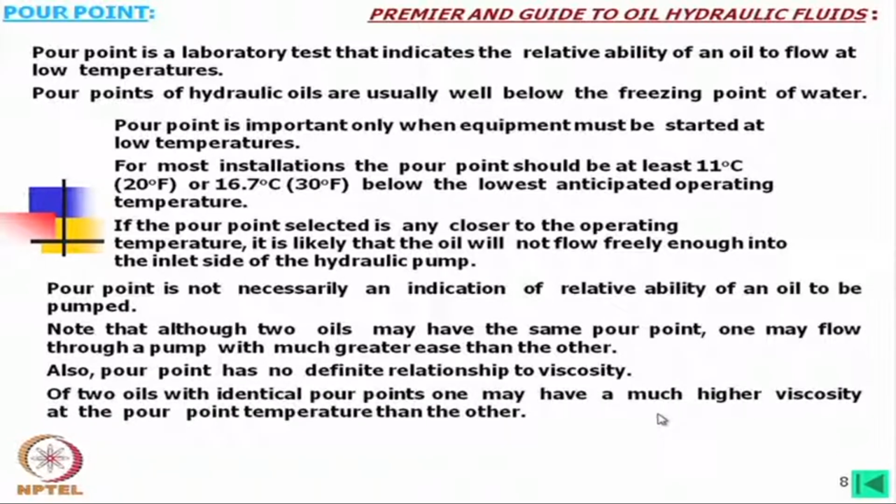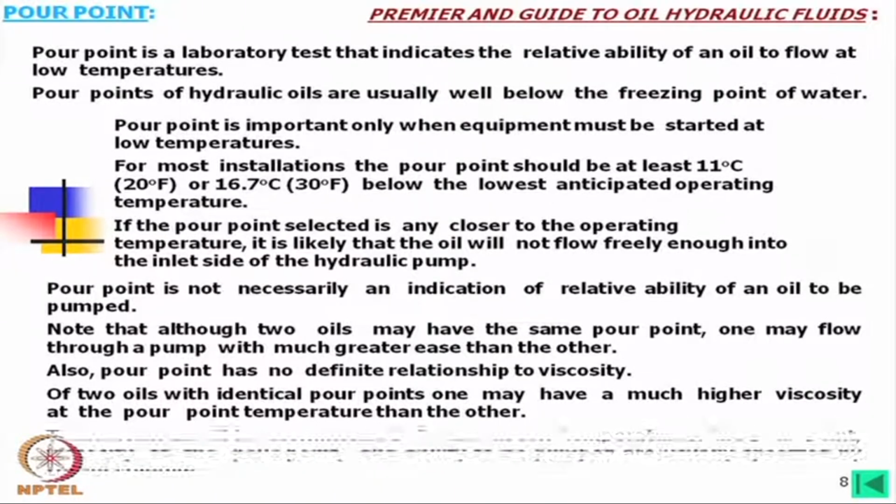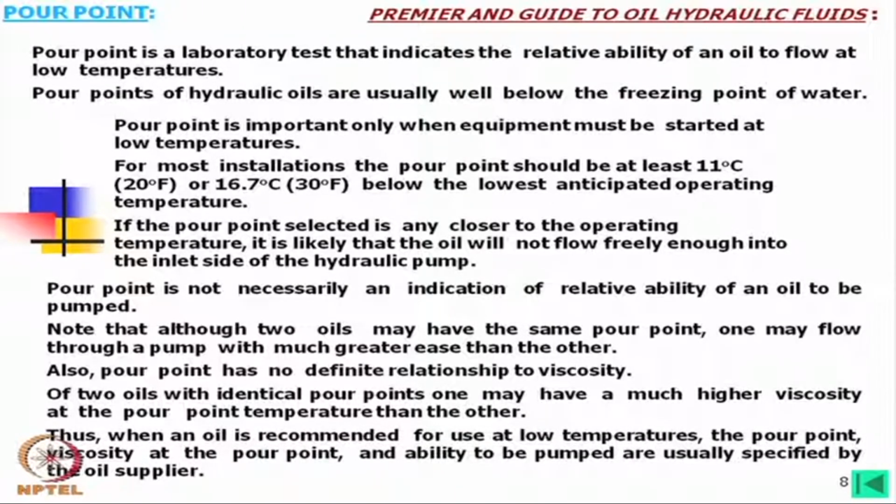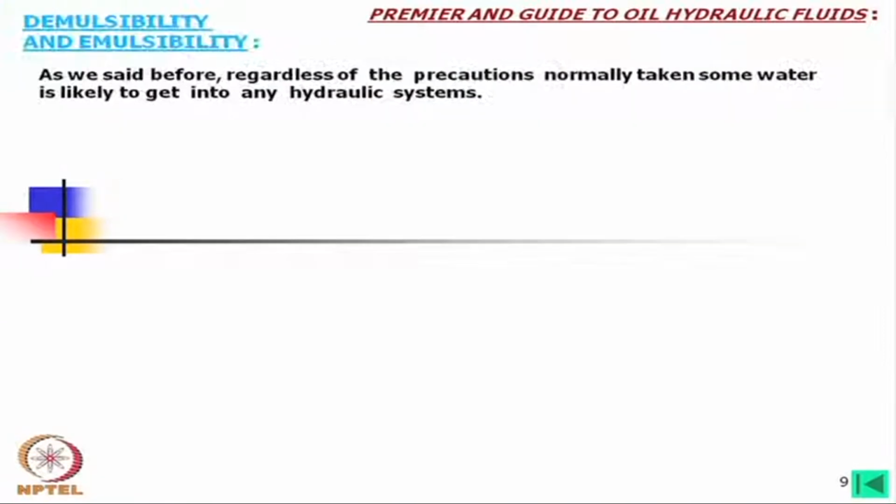Of two oils with identical pour points, one may have a much higher viscosity at the pour point temperature than the other. Thus, when an oil is recommended for use at low temperatures, the pour point, viscosity at the pour point and ability to be pumped are usually specified by the oil supplier, or rather we should say the oil manufacturer.